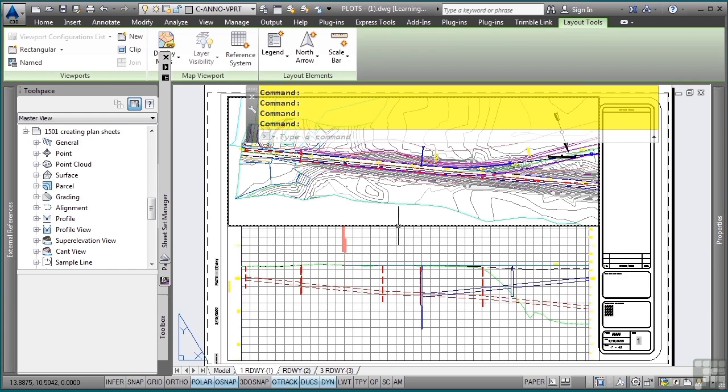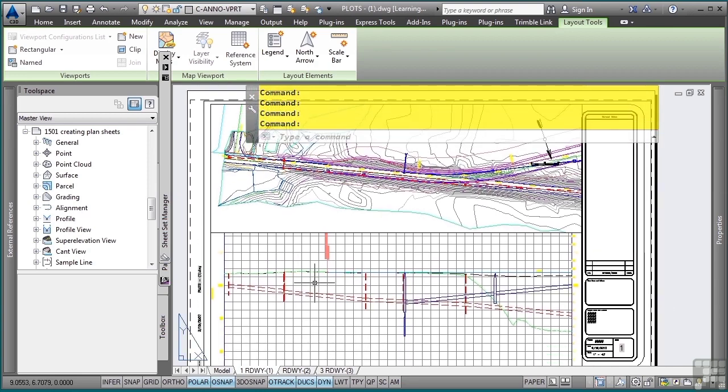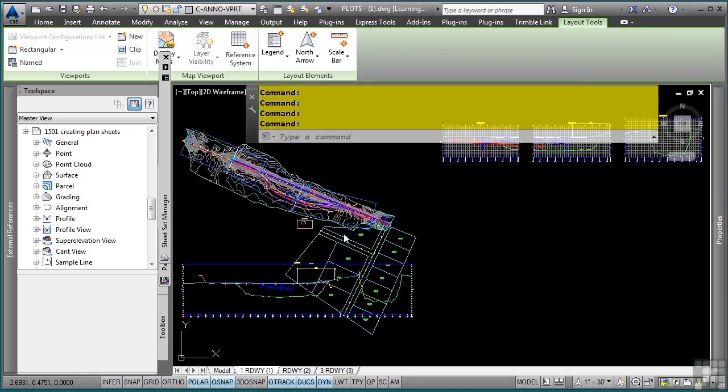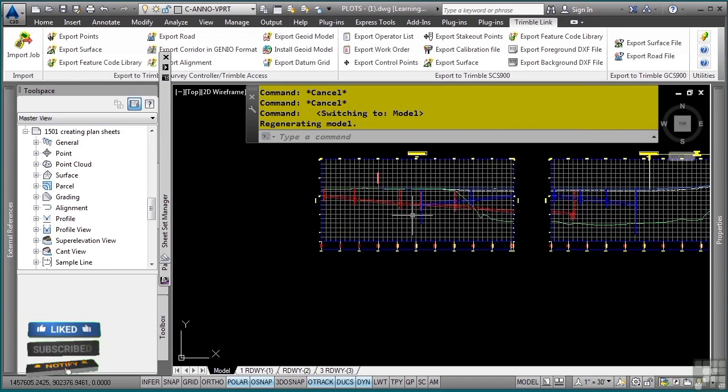And as I always say, the plan creation tools provided by Civil 3D get you about 85% there. After that, you will have to make some minor edits. So for instance here, just to give you an example, you'll notice that my profile view is not displaying my band, and I also have some layers that are thawed and so on. So if I go back to my model space, remember all that it did was it referenced in the file that we were in to create these sheets, and it put profile views here with data shortcuts to all these different objects.